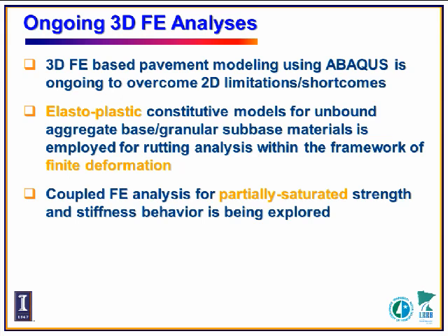And in terms of permanent deformation, all the previous research is based on the small deformation theory. So another thing we can try to do is analyze permanent deformation using an elastoplastic constitutive model within the finite deformation framework. Another possible way for us to explore is how we can incorporate the unsaturated soil mechanics into the finite element analysis. So right now, those three directions are the ongoing research directions.